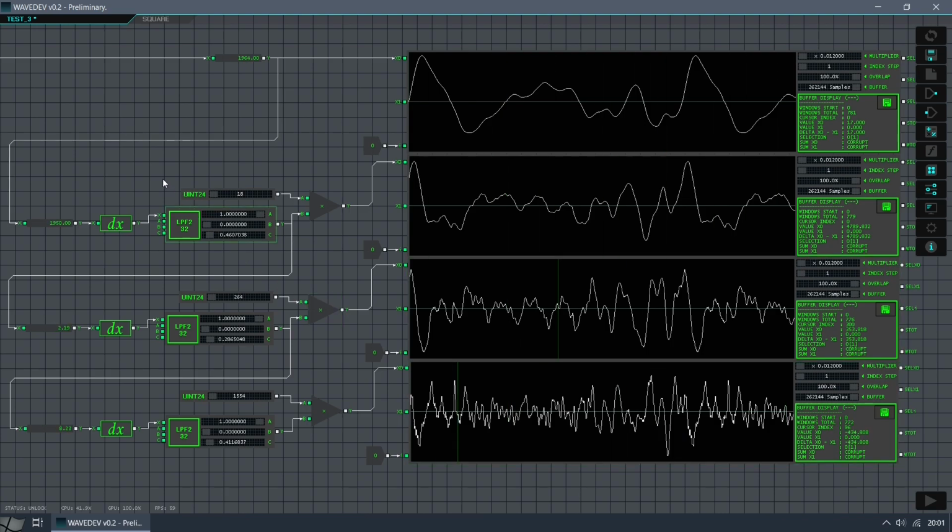So, this experiment consists of applying 3 stages of first-order high-pass filters in series. The first signal is the original, as a reference, and the others are the outputs of each stage. I ordered them vertically to have a better panorama. All the instruments have the same scale. I have to amplify the signal more and more to keep them at a similar amplitude. So this last signal is very small compared to the original one.